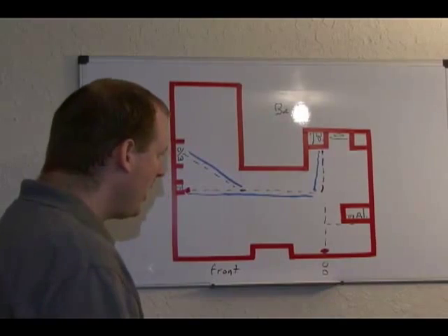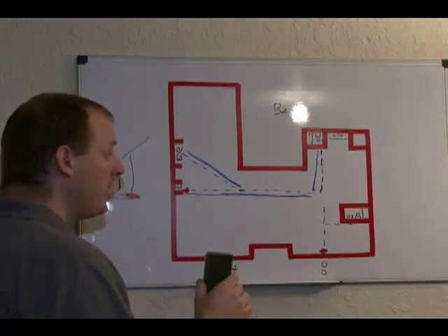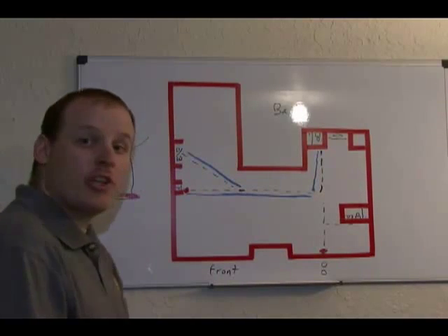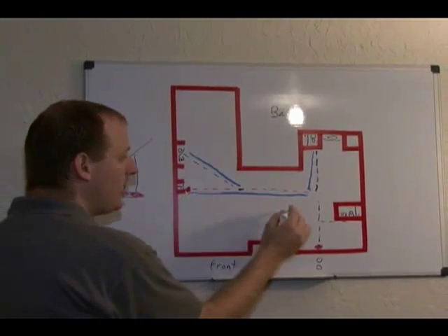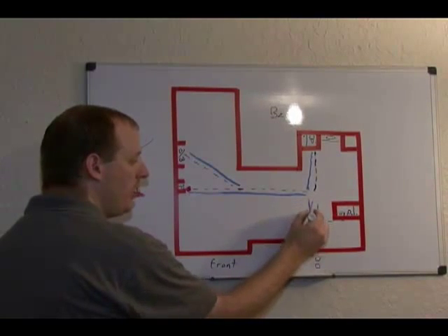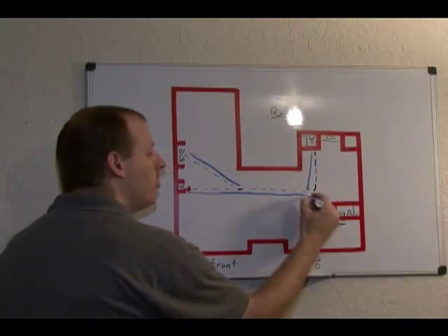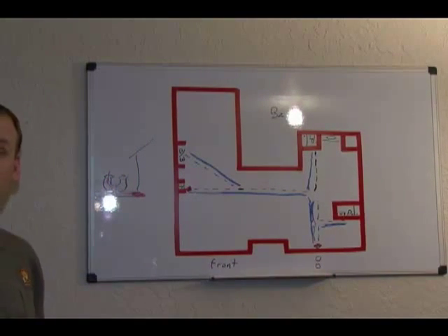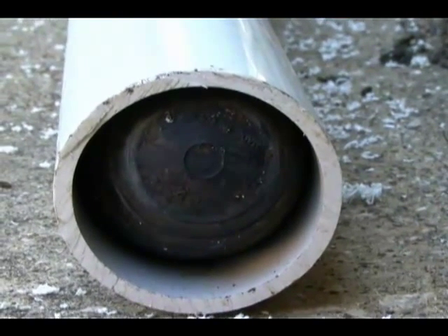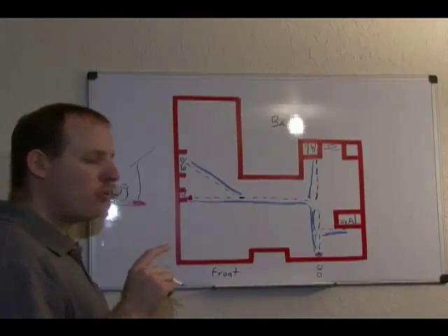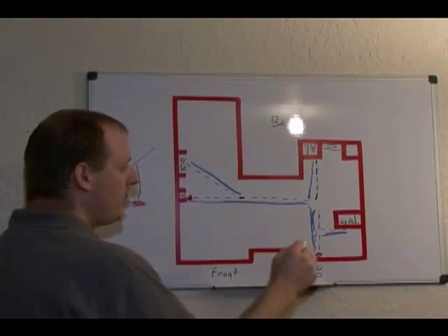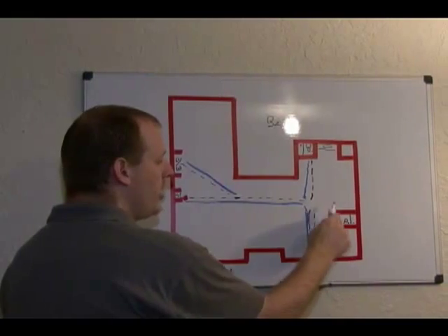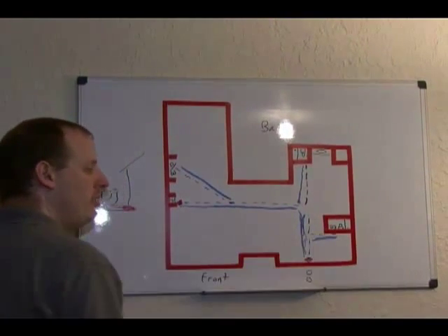Okay? And at this point, we would then test the entire system with water to see if there are any other leaks than the leak at the kitchen sink. Okay? So we would then be testing all of the lines under the house, except for our kitchen sink, which is again blocked off. Okay? At that point, as we know from our preliminary information, we have a leak over here. Okay? So we would then know that it would show a leak in the lines.